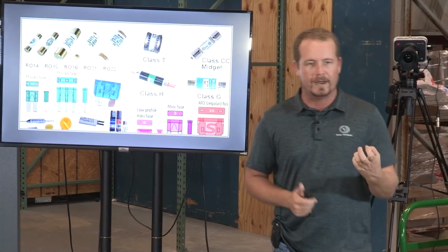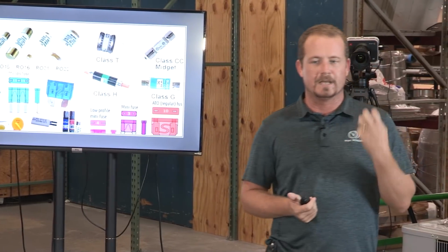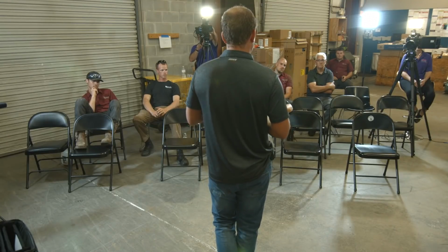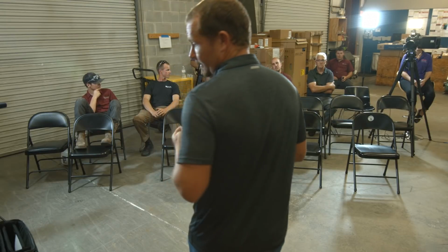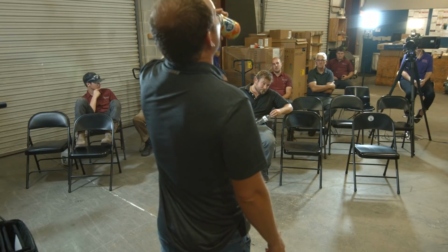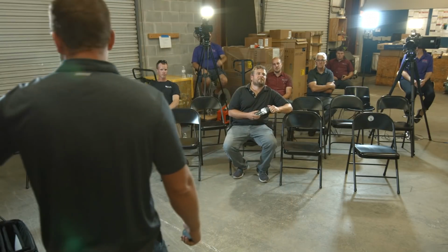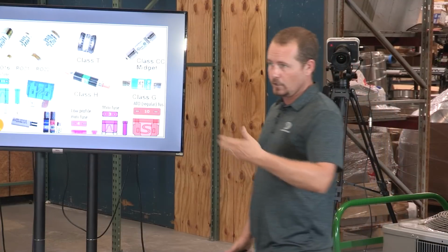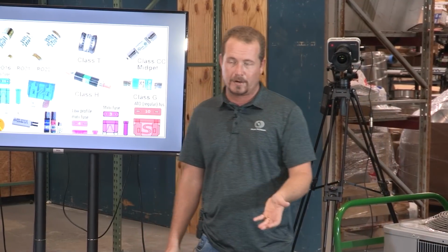Now, what is that voltage rating on a fuse? What does that represent? Sam, voltage rating on a fuse. Why is there a voltage rating on a lot of fuses? It's usually pretty high, too. Because voltage doesn't blow a fuse, amperage does. Amperage is what blows a fuse, right? The current is what blows a fuse. But why do they have a voltage rating?